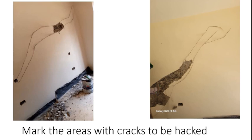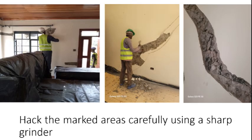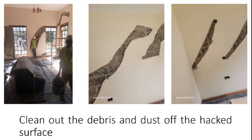So you mark the areas with cracks to be hacked all around, and then you hack the marked areas carefully using a very sharpened grinder, as you can see, and again inspecting to see that that activity is not causing other problems. Are the rest of the surfaces intact? And you continue like that and give the walls or the areas which have been affected time to settle down. And you continue until you clean out the debris, dust off the hacked surface, and expose that area.